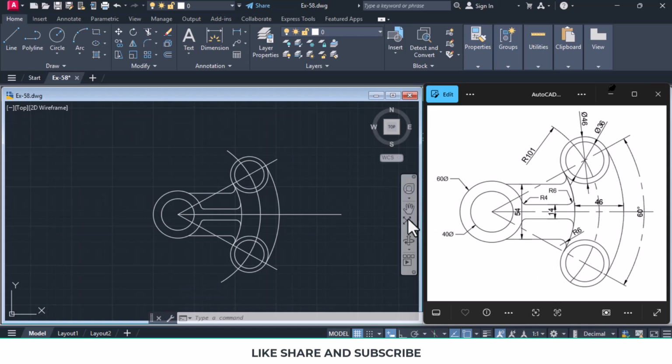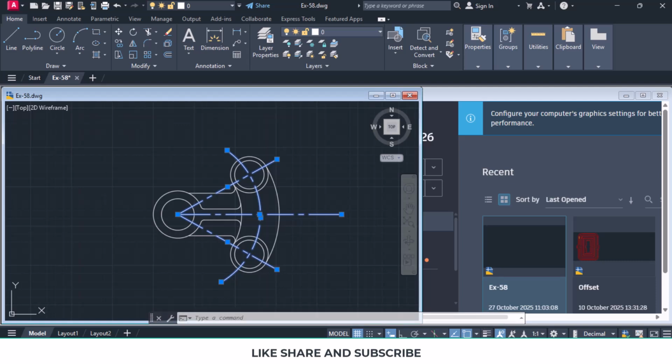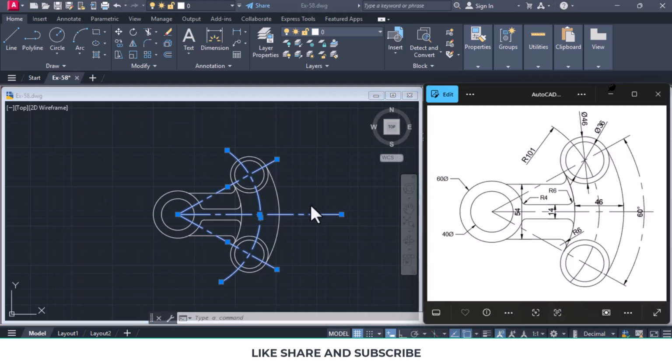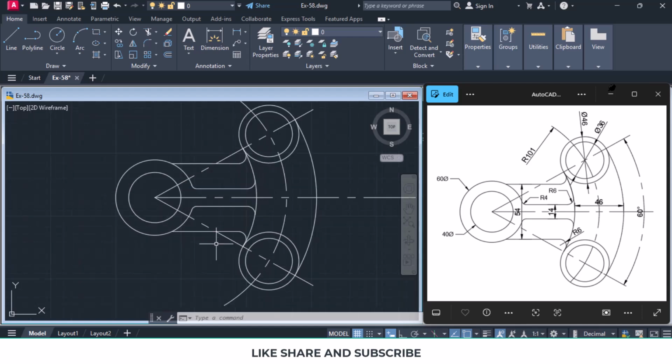Now we have to change the line types. So we want to change this to center line. We want to change this to center line. We want to change this to center line and this to center line. So we have selected all the line objects. Then we click on properties, and in properties we change the line type to center. So line types are changed. Press escape to come out of this. So our geometry is now complete.